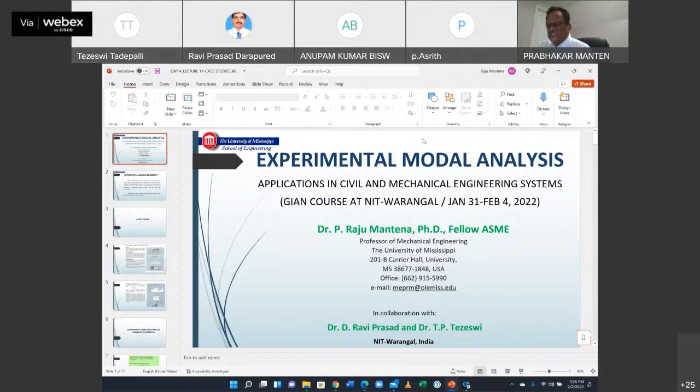At that resonant condition, the spike will move away into two separate frequencies on either side. You can make it broader or narrower by the ratio of the mass of the tuned absorber to that of the original mass. All these go into effect to move those frequencies. So it's a very common usage of this tuned absorber.